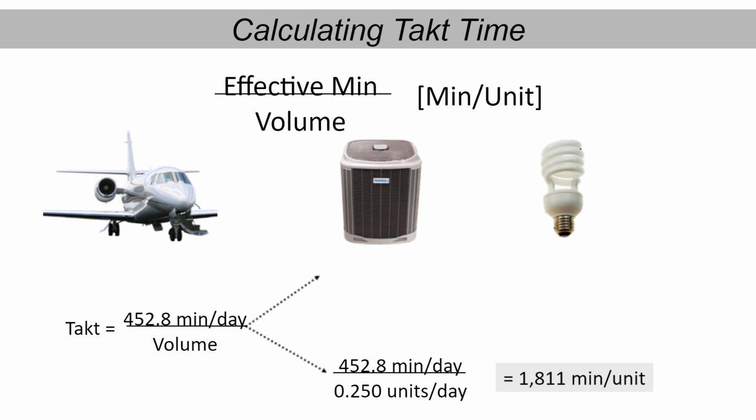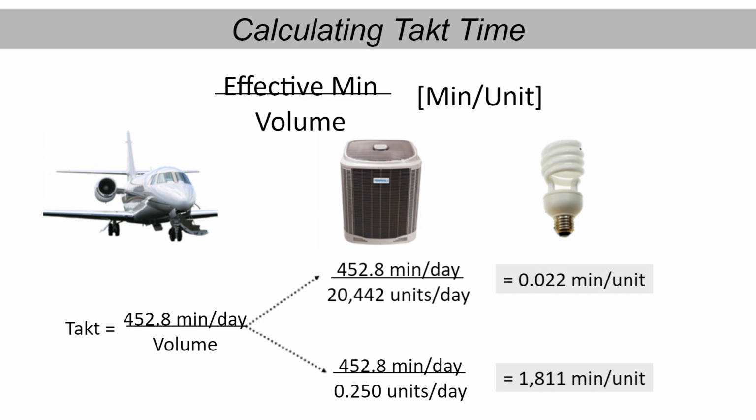High volume. Can you picture yourself working at a rate of 0.022 minutes? That is 1.2 seconds per unit. Can you? I'm sure you're laughing and saying, no thank you, right now. And you're right to feel this way. When takt gets into very small numbers, you need to start thinking automation. Very short takt time lines are also very challenging to balance, since there is no time to overcome natural human variability.